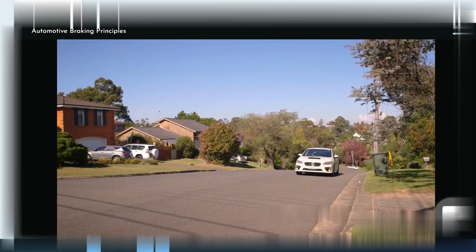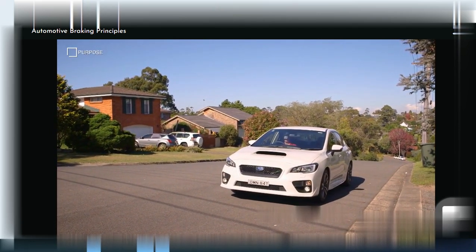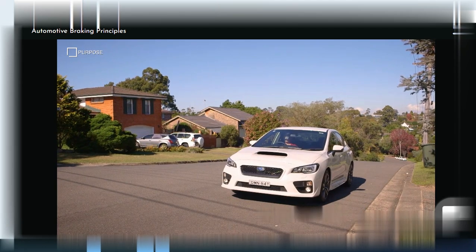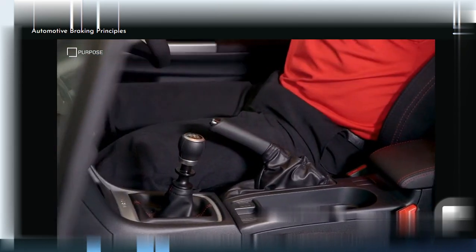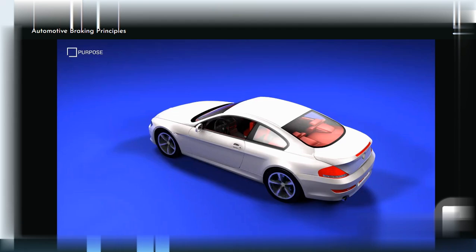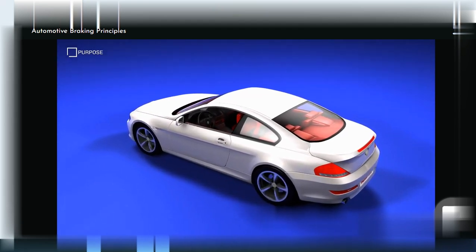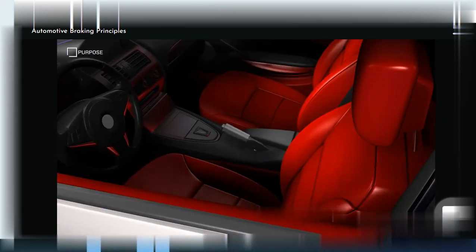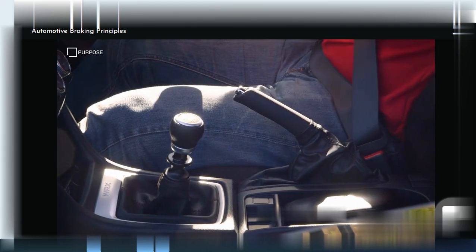We know the purpose of the vehicle service brakes is to slow or stop the car within a reasonable distance from different speeds. The emergency or park brake is a separate brake system designed to help arrest the car's movement through driver input if the service brakes fail. The emergency or park brake is also used to hold the vehicle stationary once momentum has ceased. System designs will vary, but some components are shared between the service and emergency brakes.